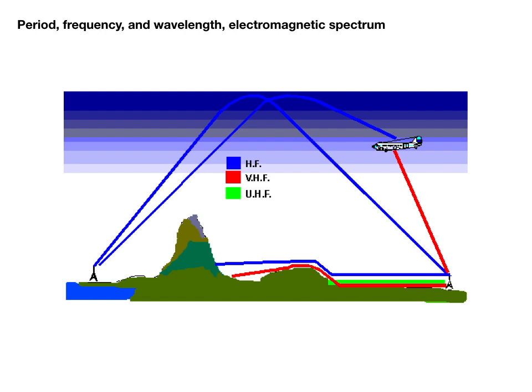To become an effective amateur radio operator, you need to familiarize yourself with the different amateur radio bands and know which bands to use to achieve specific communications goals. As mentioned earlier, the amateur radio bands in the HF portion of the spectrum are most often used for long-distance, over-the-horizon communications. The reason for this is that radio waves at those frequencies are bent back to Earth by the ionosphere. The radio waves may even make more than one hop and propagate around the world.